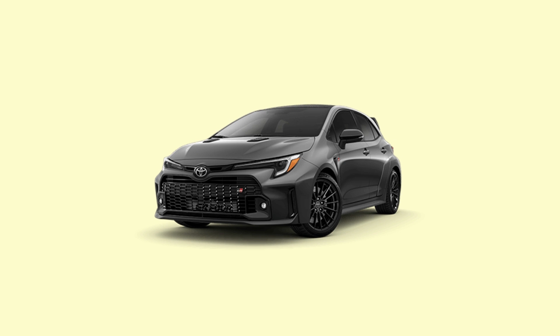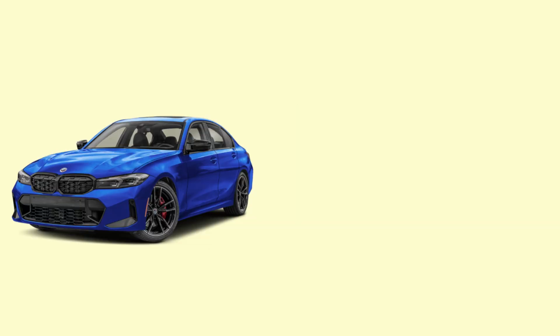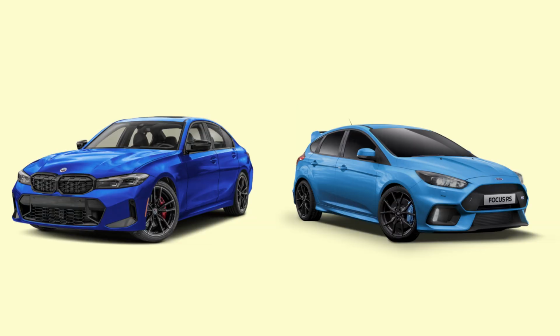Toyota, for instance, in a GR Corolla, has a sport mode where 70% of the torque is transferred to the rear wheels, whilst in some all-wheel drive systems such as BMW's xDrive, and even the late Ford Focus RS in drift mode, you can even distribute all of the available torque to the rear wheels, essentially transforming the car via software into an FR layout, and thus getting the weight distribution closer to the ideal 50-50, which we will discuss in the FR section.